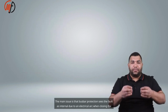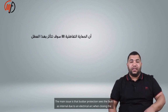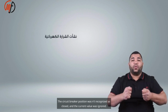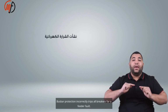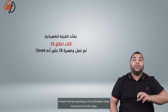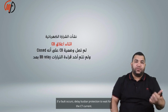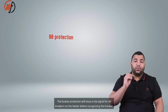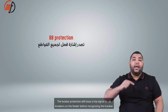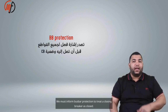The main issue is that busbar protection sees the fault as internal due to an electrical arc when closing the circuit breaker. The circuit breaker position wasn't recognized as closed and the current value was ignored. Busbar protection incorrectly trips all breakers for a feeder fault. Prevent this by inputting a circuit breaker close command into the relay. If a fault occurs, delay busbar protection to wait for the CT current. The busbar protection will issue a trip signal for all breakers on the feeder before recognizing the breaker as closed. This is incorrect. We must inform busbar protection to treat a closing breaker as closed.